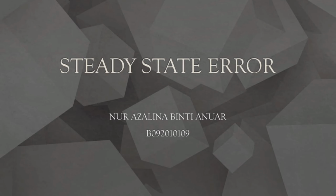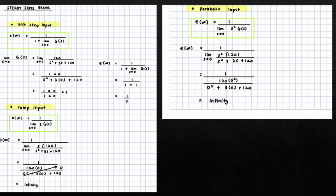Next, we are calculating the steady state error. For our system, we are using a closed loop system, so we can calculate the steady state error using the final value theorem. Now, let's plug in the Laplace transforms for some standard inputs and determine equations to calculate the steady state error for the system. We need to do three equations. The first one is step input, and we got the answer is a constant value.